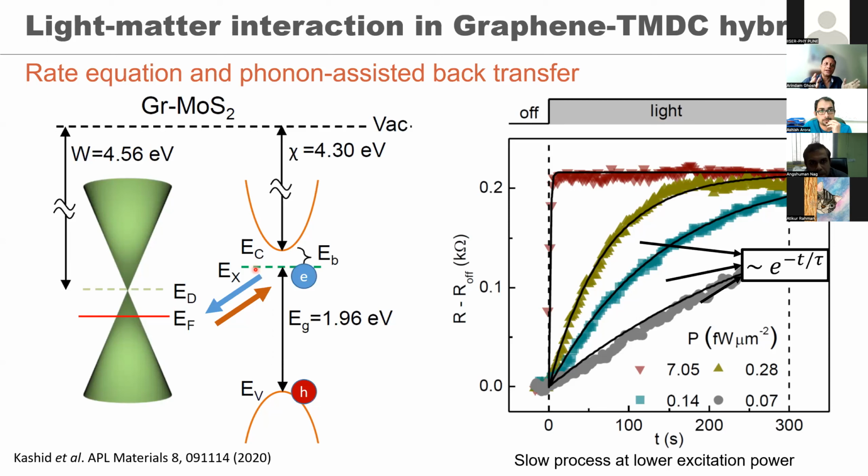This is one of the key goals of this field now, to see how we can sensitize this to infrared or even longer wavelengths. What I showed you today is purely photoconductive. What I did not show you, because that work is going on, is using bolometry. In principle, we should be able to go to much longer wavelengths, because we will start using heat as our observable. But that's going to come up later.